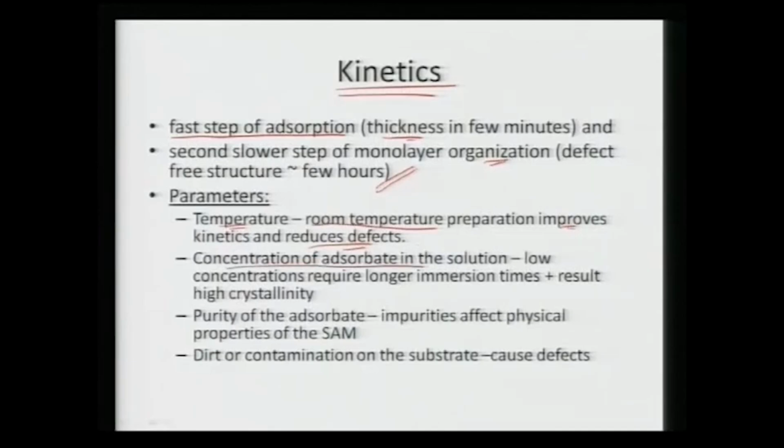Concentration of adsorbate in the solution: if you have low concentration, it might require longer immersion time, but it will result in high crystallinity. So, that is coherent with the lower temperature. Again, if the adsorbate is very pure, then the overall physical properties of the SAM can be much better or much more predictable. So, that can also lead to conformation of the coating to a certain requirement. Dirt or contamination on the substrate can also cause certain defects.